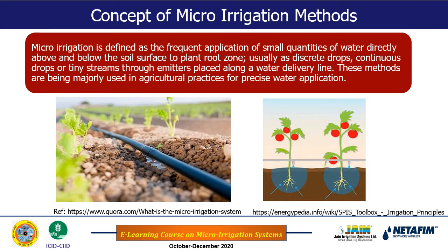But towards the end of the 2 week irrigation period, again the water content in the root zone will drop below the desirable level. We call this the allowable depletion level. It will drop below the allowable level or desired level, and it may reach up to the wilting point as well. And if it reaches the wilting point, the plant will be subjected to higher stress.